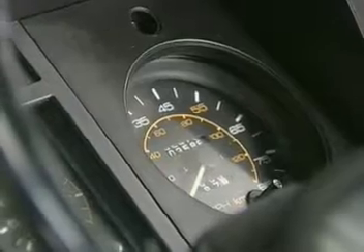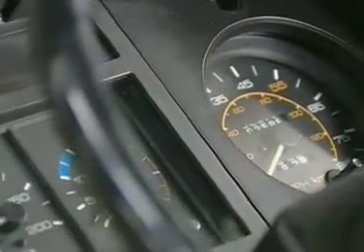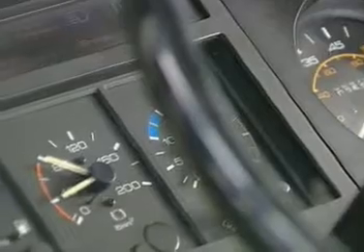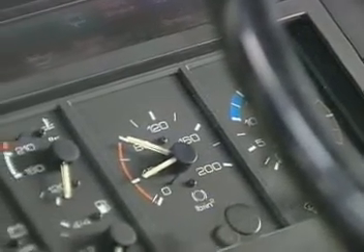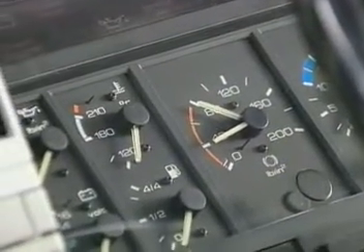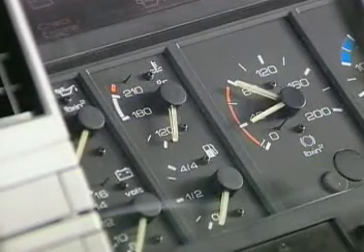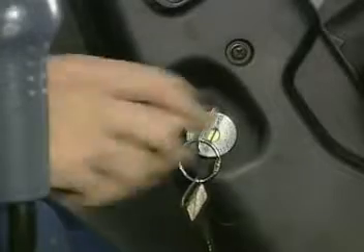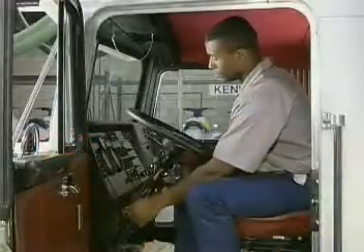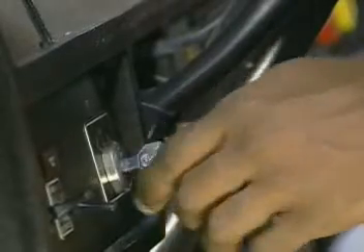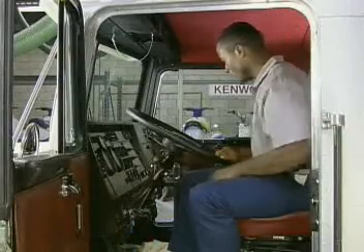The accurate operations of gauges and warning lamps and operator controls are crucial to the safe operation of the vehicle. Start your inspection of the cab-mounted instrument cluster by doing a bulb check. Turn the ignition key on and check to make sure all warning lamps operate. Then start the engine and allow the engine to run as you monitor the operation of all of the gauges.